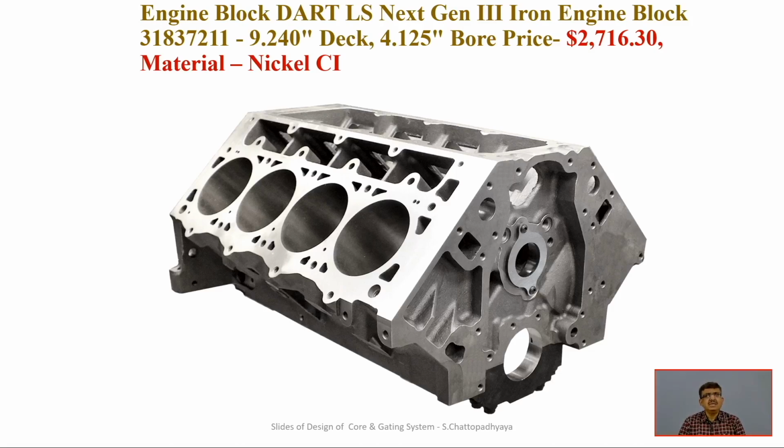It is not a near net shape manufacturing product, but whenever the core is appropriately placed, that ensures that a good amount of machining does not have to be carried out. The machining part is very limited. The reason is that those hollow sections are already created by the core.